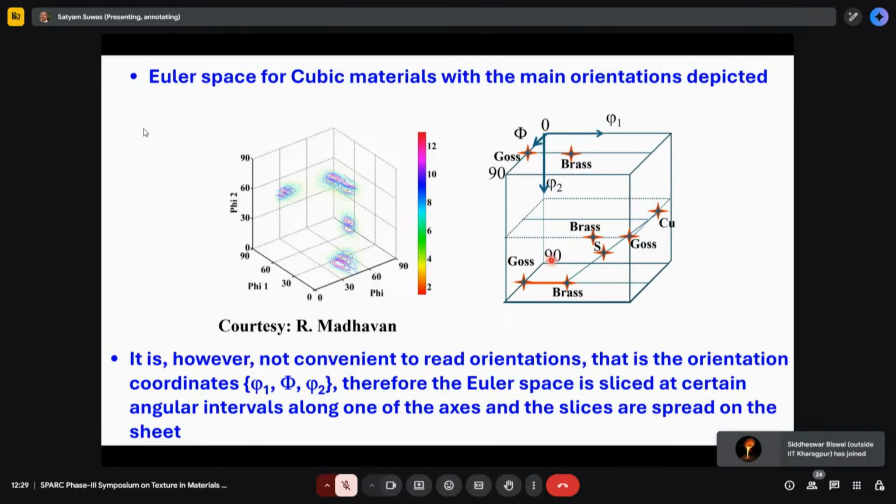And then what you do is, each peak corresponds to one set of Euler angles, and then you identify the location, because each set of Euler angles is related to HKL UVW. So these maxima will relate to a specific crystallographic orientation. Here a general standard set of FCC orientations is given.